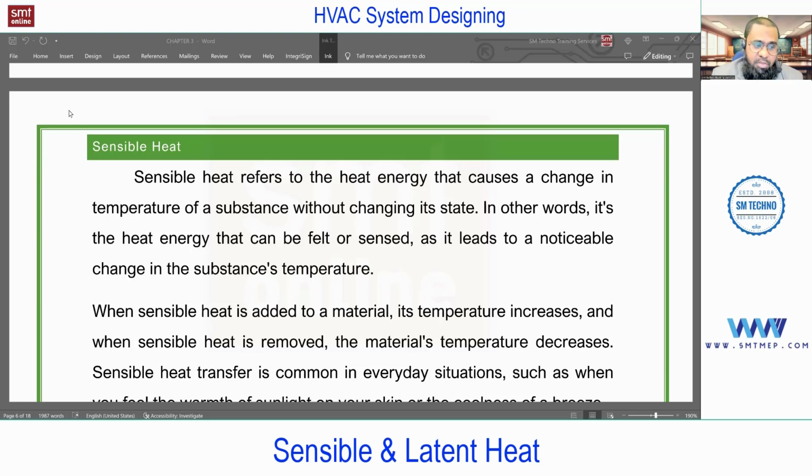According to that, we have formulas. For example, heat gain through wall. Remember, it's only sensible. But what is sensible, we have not discussed yet. We'll discuss, don't worry. I'm just trying to give the importance of this topic. Similarly, heat gain through ventilation is not just sensible, it's sensible plus latent, because the moisture is also involved. Similarly, heat gain through people is sensible plus latent.